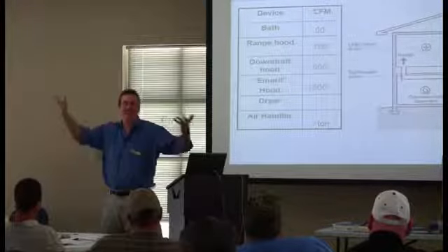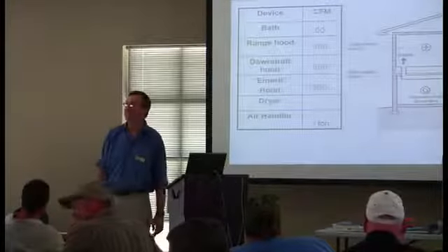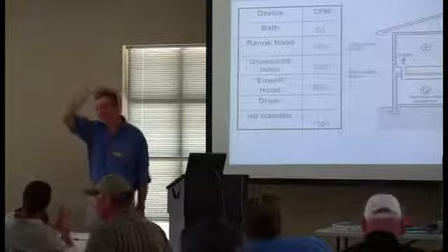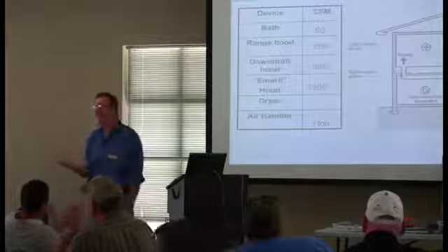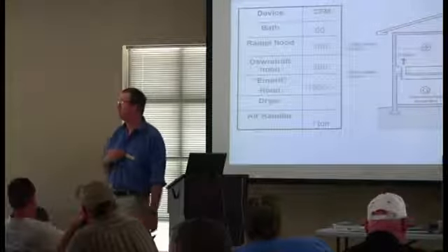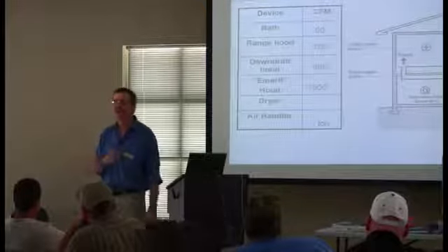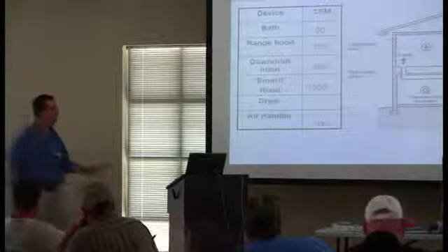2,000 CFM is a blower door, y'all. That's a big honking fan. So that's a diagnostic blower door. It's a tool, right? Exactly. What's ironic to me is if that fan were installed in a commercial building, guess what it would have to have? Makeup air, right? But in a home here, we can violate physics. So you have to be careful.